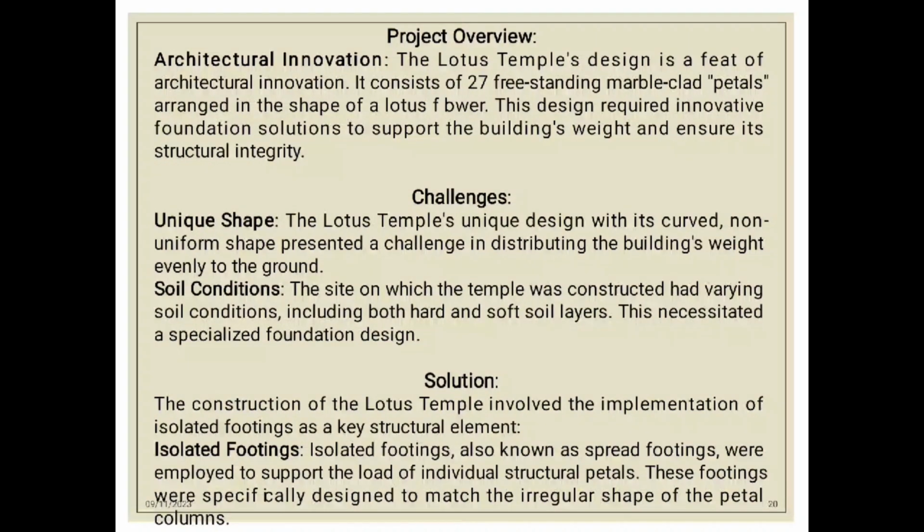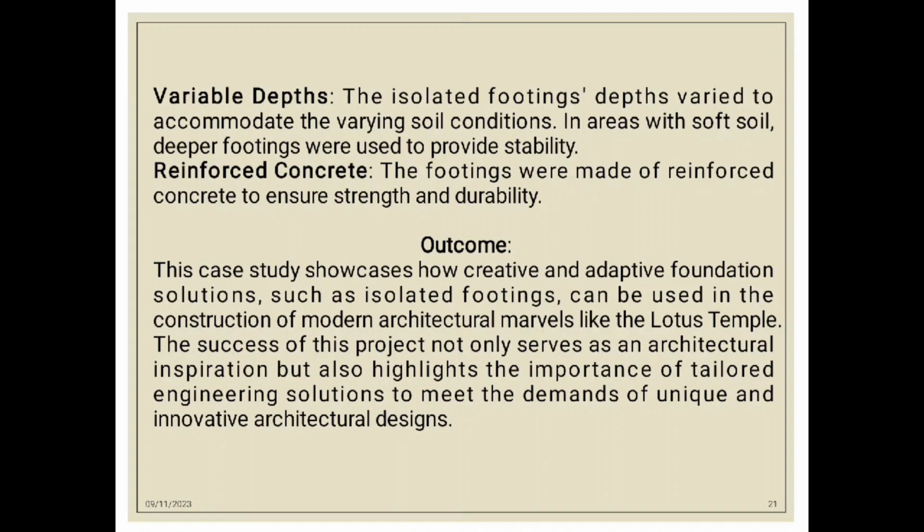Variable depths. The isolated footings' depth varied to accommodate the varying soil condition. In areas with soft soil, deeper footings were used to provide stability. Reinforced concrete. The footings were made of reinforced concrete to ensure strength and durability.